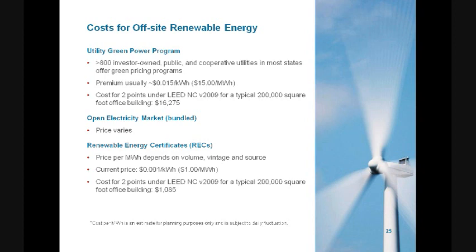So just to back up a little bit, it sounded like you were getting moving a little bit towards whether or not you're actually purchasing the green power specifically through a utility program. So just to point out, regardless of whether or not you're participating in a utility program or buying from a third party, it's still a REC, so that's a key feature. Because as we mentioned, the utility is going to have a mixed grid, and so they're going to be generating a certain number of megawatt hours of green power. And in order to say to the customer, you bought X number of megawatt hours of green power, they have to retire and retain those RECs, much like you would do for the on-site solar. So a REC is a REC, depending on where you look at it. It's just how it's treated.